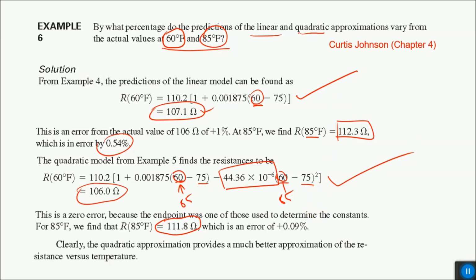And these formulae will be applied inside your microprocessors or microcontrollers. So you will be solving for T, and this would be your subject, and R will be known. If you have the value of R from the RTD and you are trying to find the corresponding temperature, you can apply this or this formula.